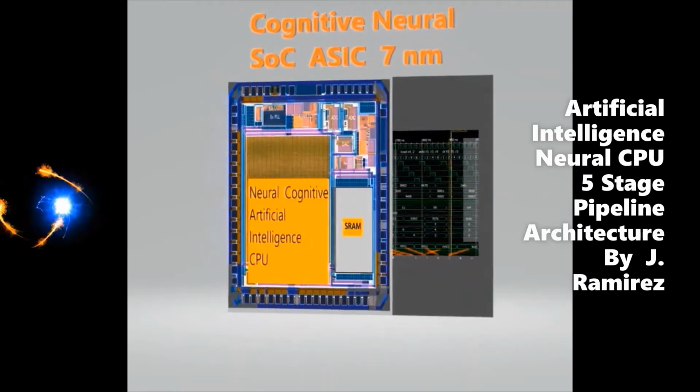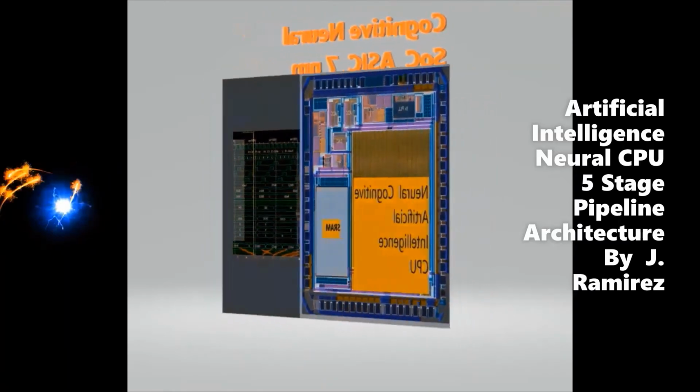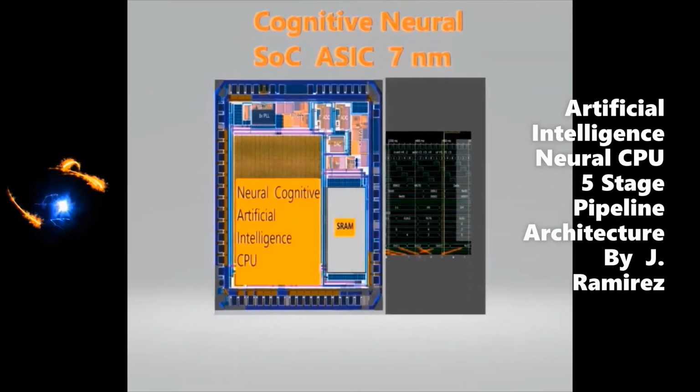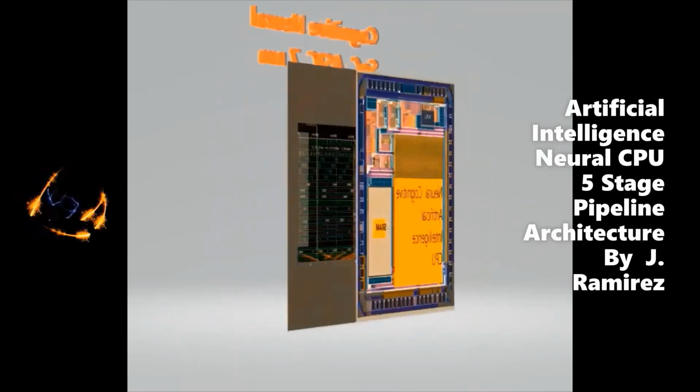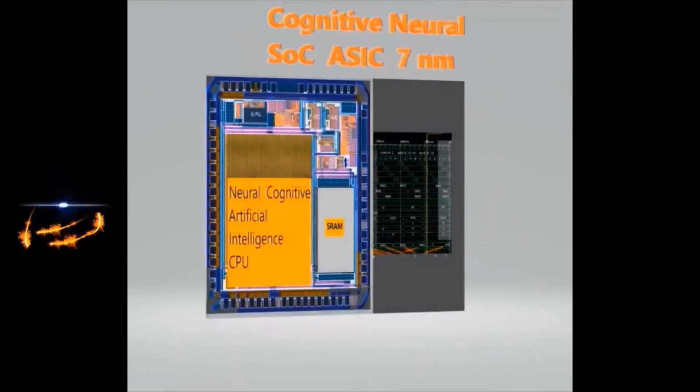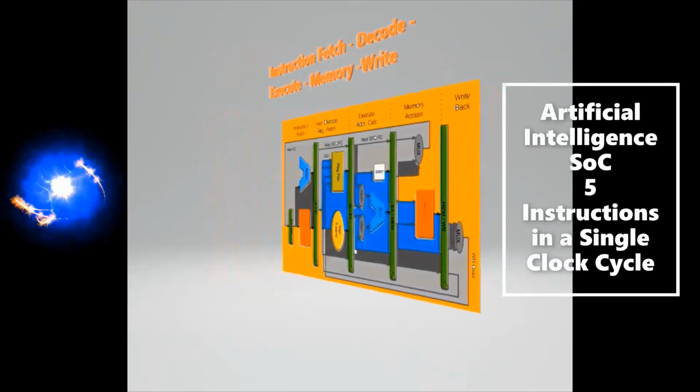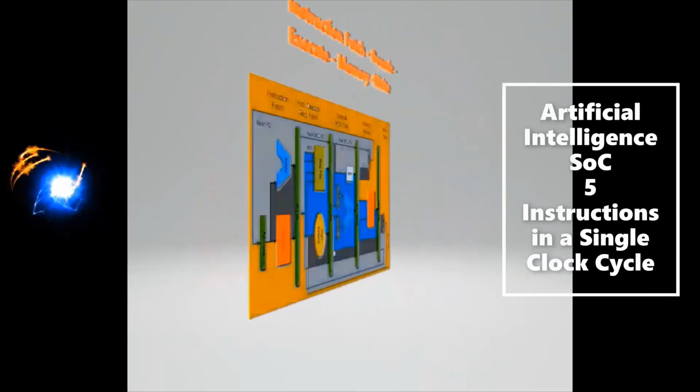And the memory stage. In this stage, the processor reads or writes data memory, so only the LW and SW instructions use this stage.